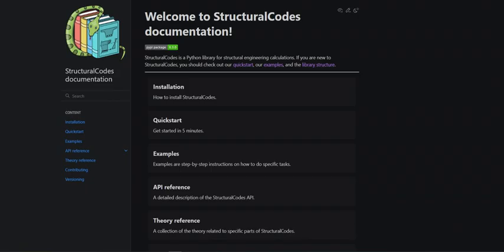And we should provide a diameter of the bar and a material. So diameter, we can do like this, and we can do a reinforcement, which was the material. And then finally, we should either provide a number of bars to add along this line or a center distance. So let's now do n equals 2, for example. Or we could even do n bars equals 2, and then we have it defined up here.